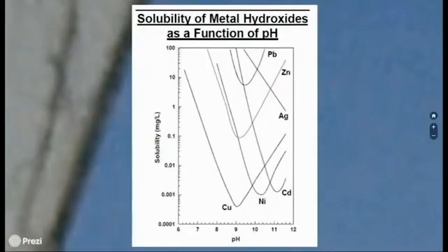And this is a graph that I had reviewed earlier, so I'll go ahead and move forward on that. The key part of this, however, is keeping in mind that certain heavy metals do have the ability to leach at high pH values and low pH values, as is the case with these large U solubility curves. The term for that is amphotericity. So amphoteric means heavy metals leach at high pH values and low pH values, but have a minimum solubility range, in this case, between 9 and 11.